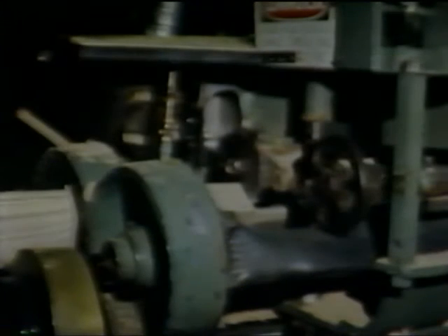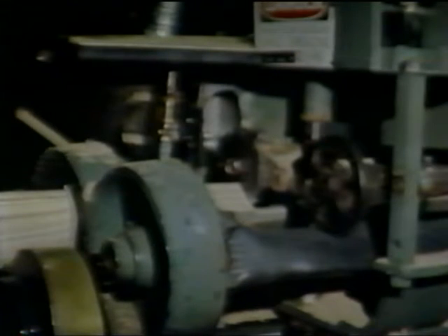Wooden propeller manufacturing starts with a blank of laminated wood, seen here at the rear of the cart. The wooden blanks are placed in a profiling lathe where a continuously rotating stylus copies the profile of the original master blade and transforms the blank into a nearly finished propeller.